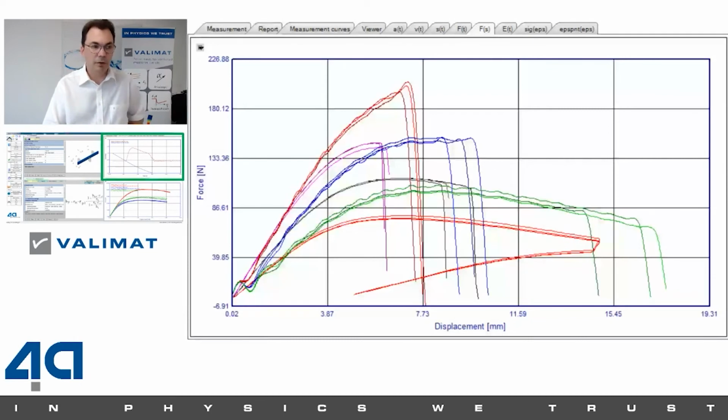So I plotted the measurement results here. You see we have static at 0 direction, dynamic at 0 direction. We have static at transversal direction, dynamic at transversal direction, and we have static at 30 degree and dynamic at 30 degree. These are the bending tests that we have, so we can directly see the influence of the anisotropy. And if we would like to model that, we could start with a simple approach. For instance, I would first start with a MAT22 card.